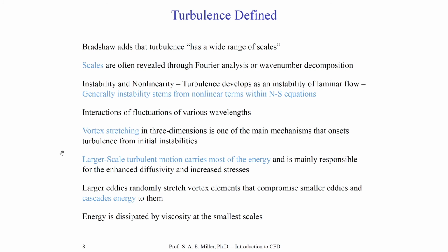The energy from the largest scales is moving to smaller and smaller scales. Ultimately, the scales of turbulence will become so small that the terms of viscosity will be very, very large for those small scales, and the energy will be dissipated through the mechanism of viscosity at the tiniest scales, and this will be transferred mostly into heat in the flow, and of course a small amount of acoustic waves, if it is compressible, which truly all practical fluids are.